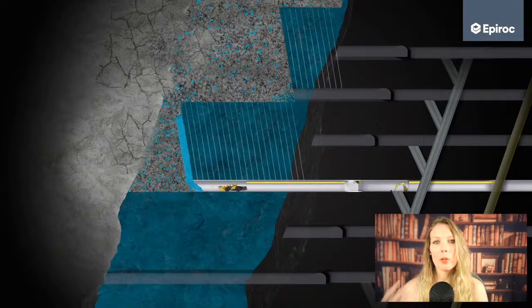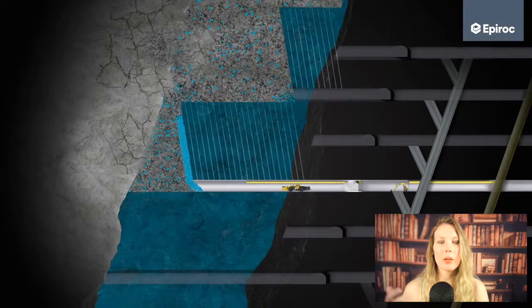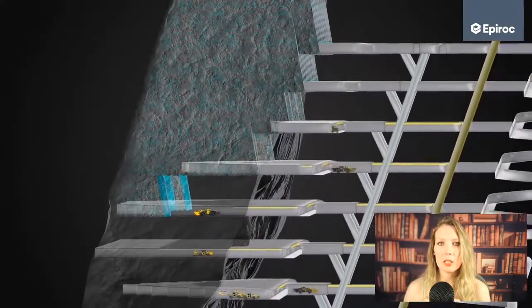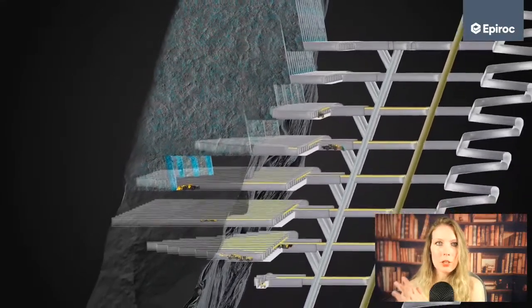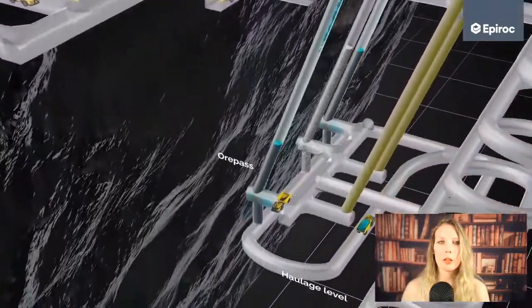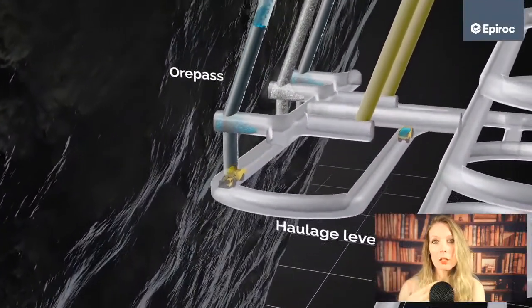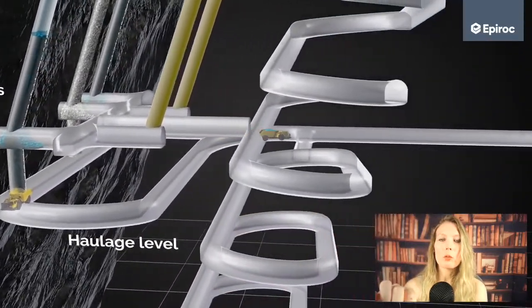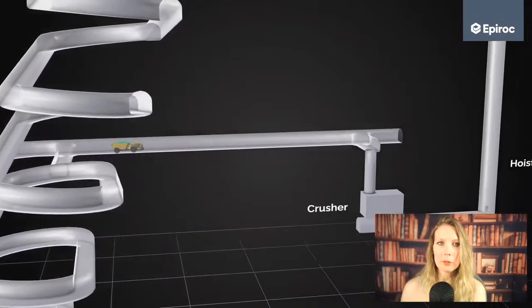On the other hand, in bulk mining methods such as sub-level stoping, backfill is used to provide regional stability, allowing multiple stopes to be mined simultaneously without causing excessive ground movement. Different types of backfill, such as paste fill, hydraulic fill, or cemented rock fill, require varying curing times and placement techniques. And if a high-strength cemented backfill is used, adjacent stopes can be extracted sooner, improving mining efficiency. However, if unconsolidated hydraulic fill is used, longer waiting periods may be required before adjacent mining can proceed safely.